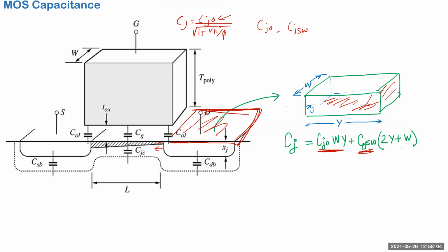All you have to provide is these parameters. When doing a schematic, you may not know the length of the source, but it assumes a standard layout. Once your layout is done, you do the extraction, which captures exactly what is drawn and calculates all these parameters.